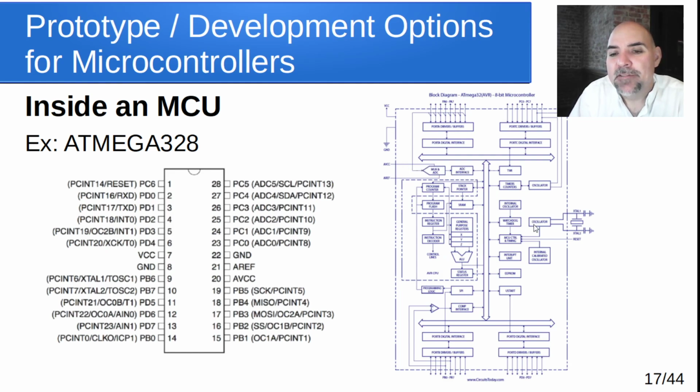And then here's an oscillator inside there. So all of this is what you get inside the chip. The only things you really need to run this design is this, and there's either a crystal on the outside, or notice it has an internal oscillator as well. You don't even need that crystal.